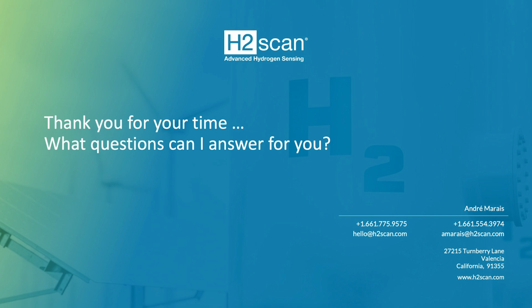So, at the end of the day, identify whether you're going to install it in oil or in the gas phase of the transformer, and identify the valves. Make sure that we know what size your valve is, and that you've got a place for us to install it. Ensure there's the ability to get power out of the transformer monitoring box, decide how you're going to communicate the data. You order the right model, and once you're ready, you walk up to the transformer, you screw in the sensor with its bleed port into the drain valve, you open the drain valve, you bleed the air, you connect the power, you connect the comms, and you're up and running.